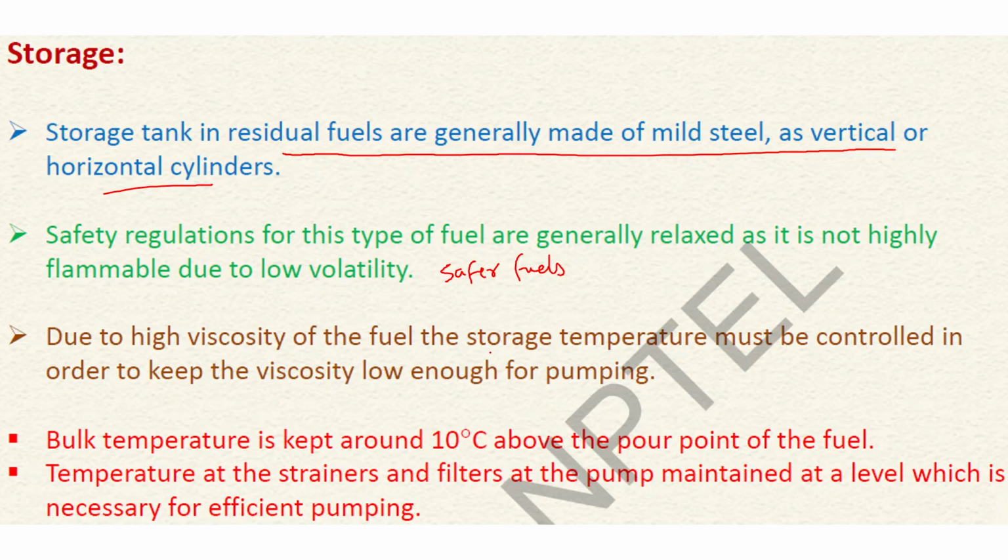Due to the high viscosity of the fuel, the storage temperature must be controlled in order to keep the viscosity low for pumping. As they are residual fuel, their viscosity is very high. But if they are used in the burners and engines, they should be able to be pumped. So for that purpose, they are stored at a higher temperature, at which their viscosity becomes low enough for easy pumping.